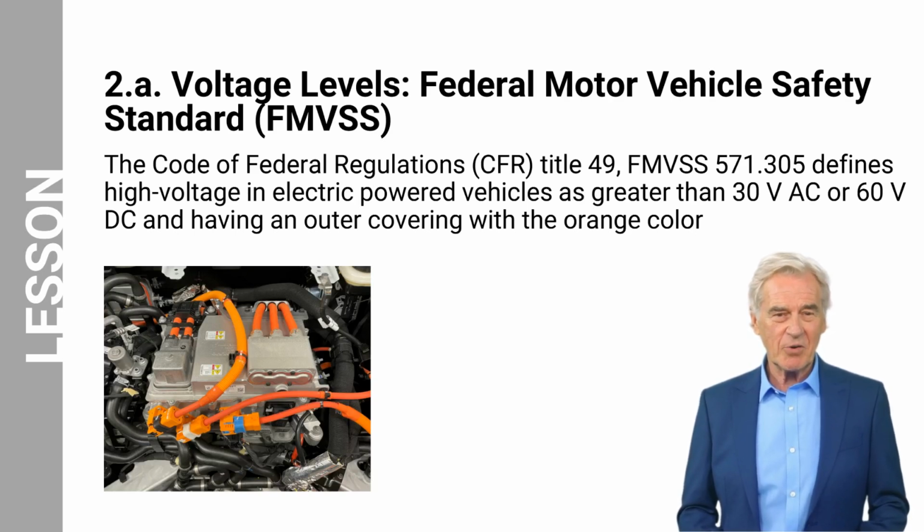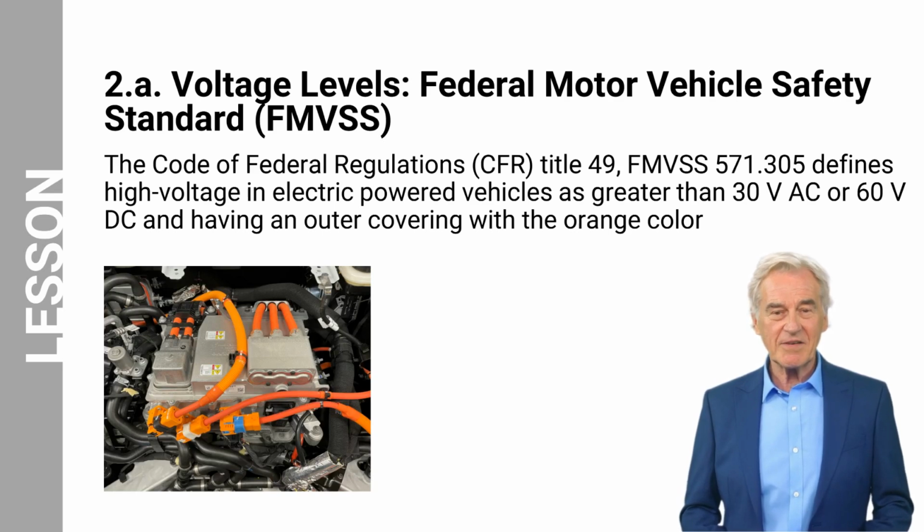The Code of Federal Regulations, Title 49, Federal Motor Vehicle Safety Standard 571.305, defines high voltage in electric-powered vehicles as greater than 30 volts AC or 60 volts DC and having an outer covering with the orange color.